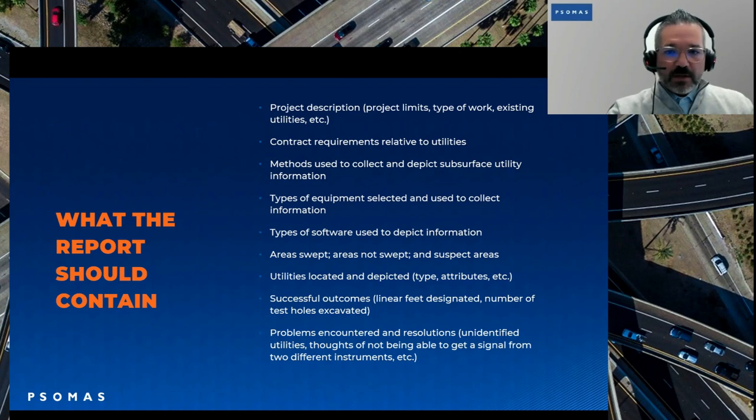What are they doing? The methods used to collect and depict the subsurface information. Did you use a GPR unit? Did you use an EM locator? Did you use the sonic wave? Did you use a magnetic locator? State what it is that was used so that everybody is on the same page.